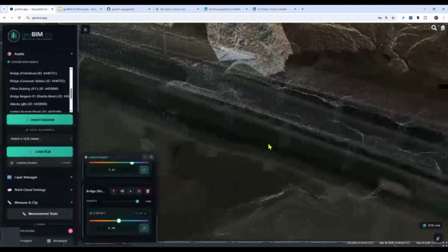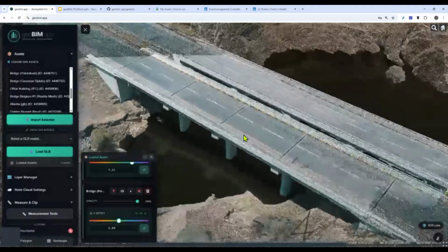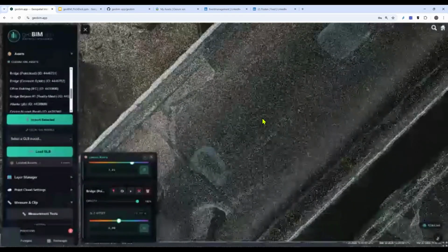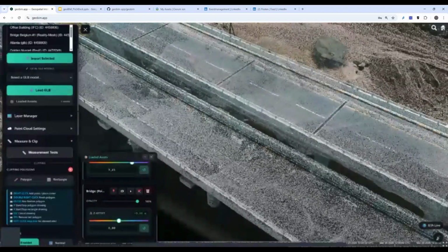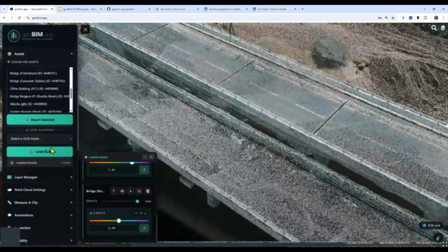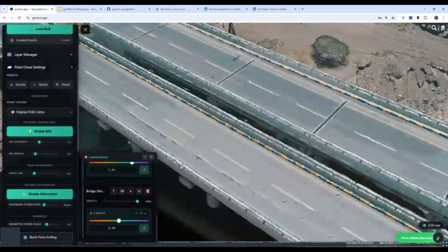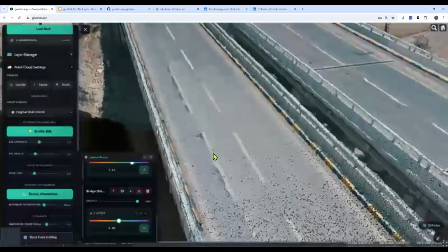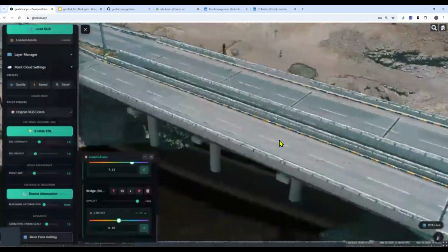And if I go closer, the problem with point clouds is always, let's say, point size. So it looks very, very sparse usually. And you can see if I go closer that I activated attenuation, it's called. So that's the distance-dependent size of those points in the point cloud. And of course, there's a little bit of a segment where I can tweak this. Let's see if that works. There we go. That's the attenuation on, and it almost looks like a closed mesh, but if you go closer, you can see the points. So that's the as-is or as-built situation of that bridge in the desert here.